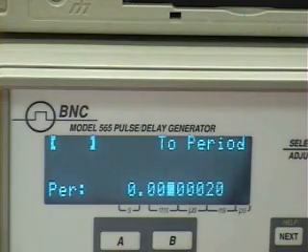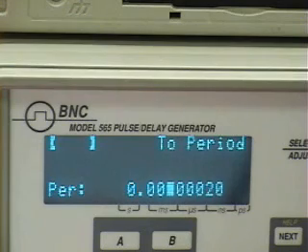The internal clocks can have a period as low as 200 nanoseconds, or basically a rate of 5 megahertz. Basically, you put in a trigger that could be internal or external. That's followed by a delay and width. If the sum of the delay and width exceeds the interpulse period, the unit will ignore the incoming internal rep rate generator trigger or external trigger until it's fully timed out.